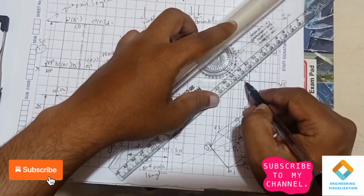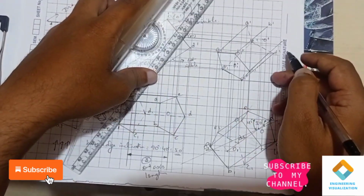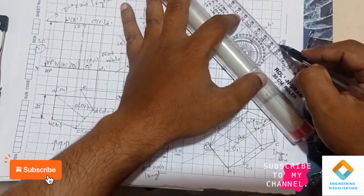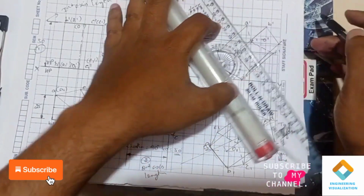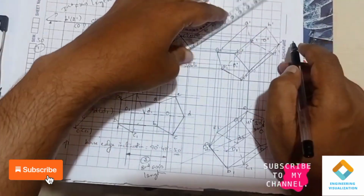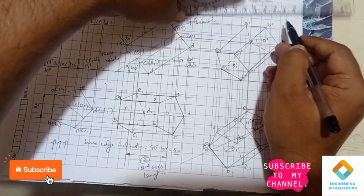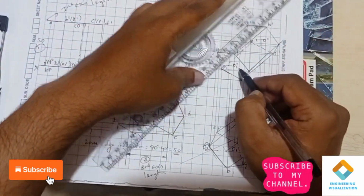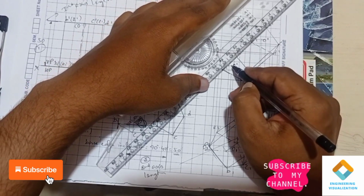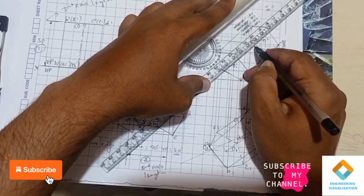That is the procedure here. You need to see whether the lines are going inside of the base of the pentagon or outside. Outside means continuous line, inside means dashed lines. Okay, so the procedure is very simple. You can follow these steps so that you can easily complete the final diagram. Okay, so finally the left one, it is the axis, that is from O1 dash to O dash, draw an axis.